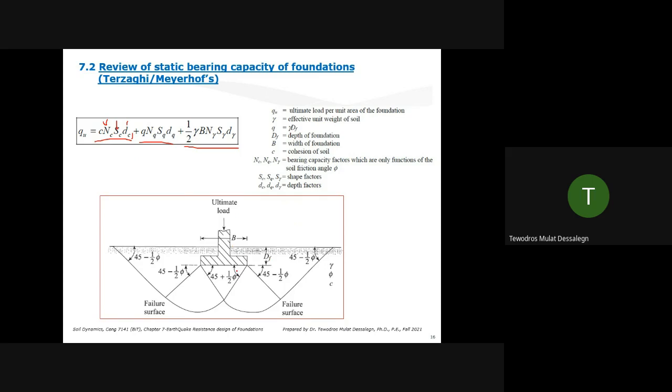In this, they are assuming a failure surface like this, the active wedge and the passive wedge, for general c-phi soil. So the idea is, if you apply a load in the static case, the soil fails by sliding through this surface, and you may see some bulging around here finally if it fails by bearing capacity, while the loaded portion is going down.